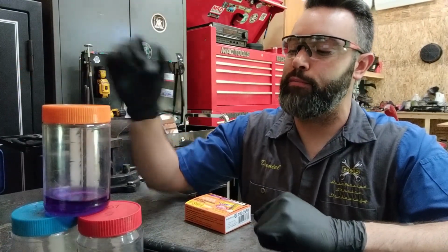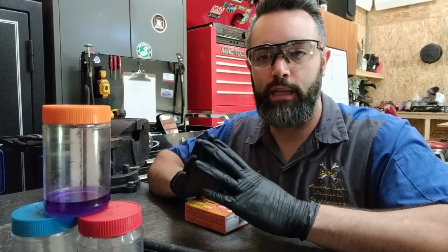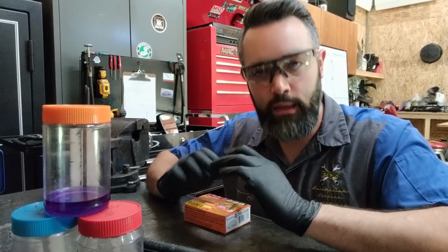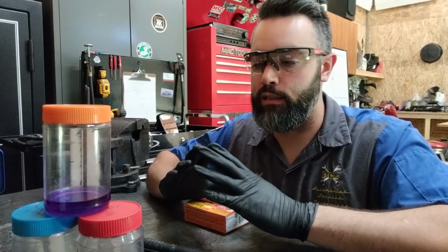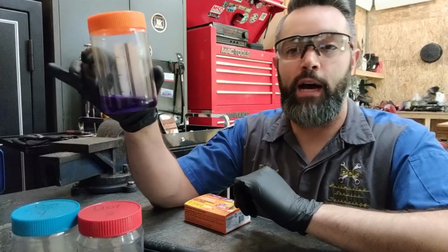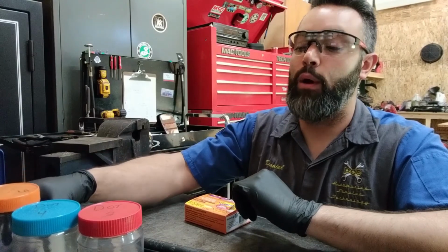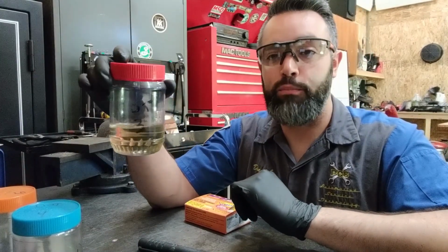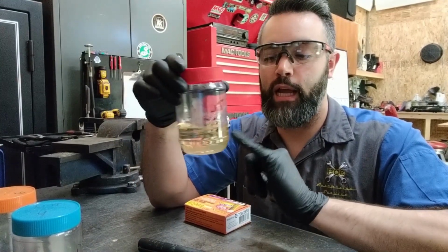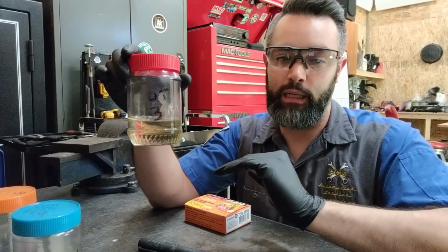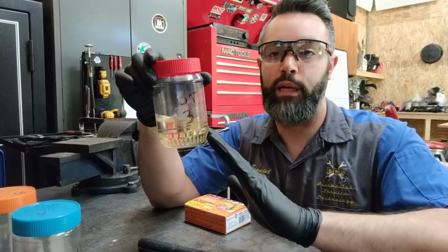DOT 5 application fluids may be used in things like motorcycles where you can have some spillover and it gets onto cosmetic surfaces, rather than inside of the engine compartment of a vehicle where it's not as cosmetic, you're not seeing things. DOT 5 silicone based fluid is not going to eat away at painted surfaces. However, most brake fluid is glycol based and it is very corrosive to painted surfaces. So if this gets onto any painted surfaces, it needs to be cleaned immediately. If you're working around painted surfaces, they should be covered and protected from any potential fluid getting onto them.